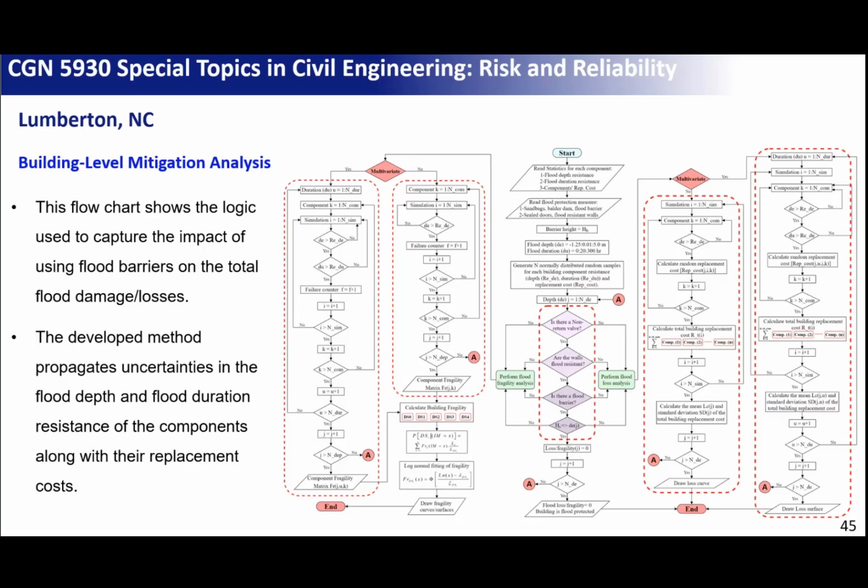Okay, and then I run a fragility and damage analysis for every component and see if this component is going to survive or not. This is the component damage analysis. I go component by component and see if this component is going to survive, if the other component is going to survive, and keep doing simulation for each component. And then I do building damage and see how much loss the entire building is going to accumulate.